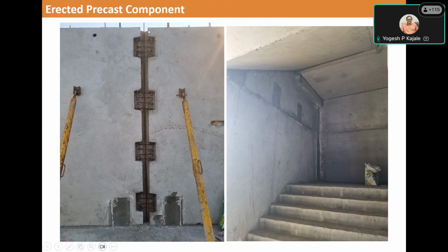The shuttering is used at this face. On the other face, there is no need of shuttering. This is what we practice because we have to ensure that every joint is filled fully. The reinforcement must be open for inspection, and only then can the joint be allowed to be filled with concrete.